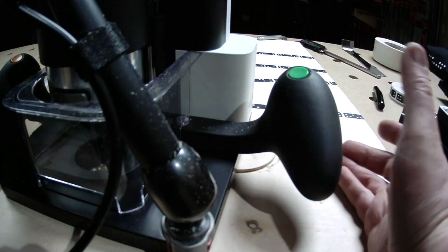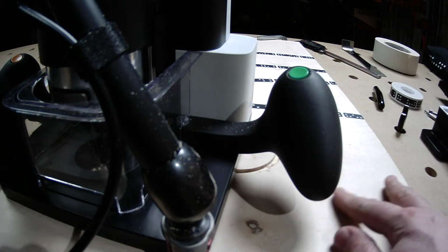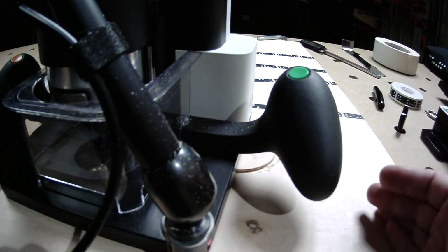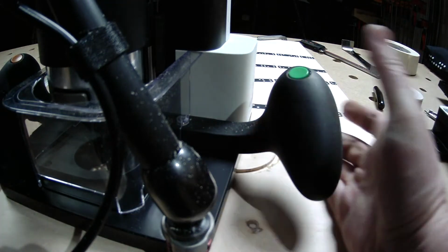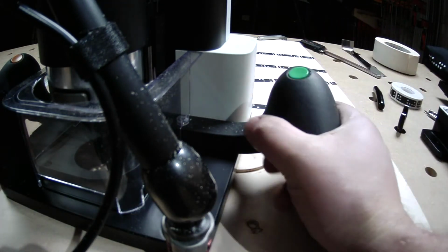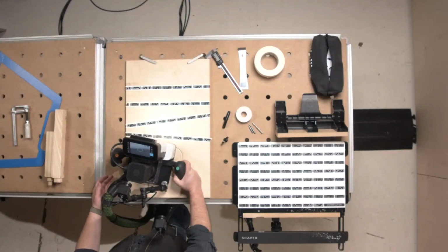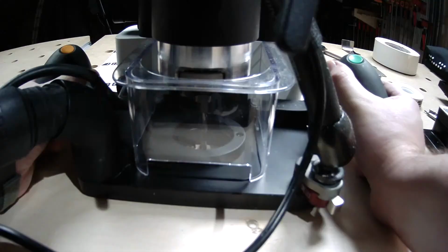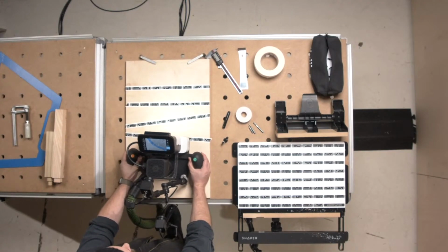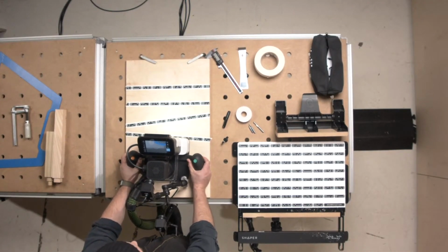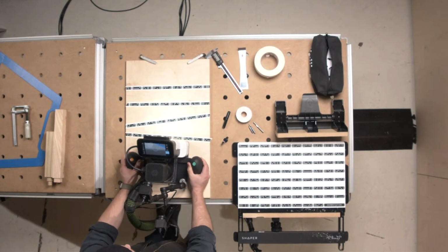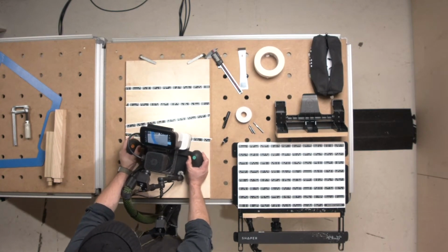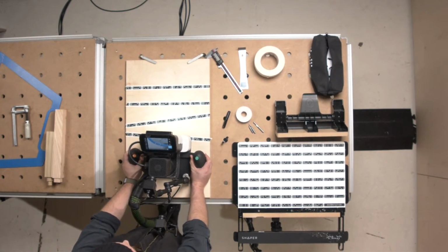What we find to be the best way to use Origin in most instances, most especially if you're doing fine detail work or coming around the corner on, say, a rectangle, is to actually plant the palm of your hand down on the work surface and hold Origin like this. That means you've got this friction area on the palm of your hand, and you can control how much friction you have by squeezing or letting loose on the handles, and that can be really helpful. It helps to control the machine going around corners, which is the more risky spot with a router.